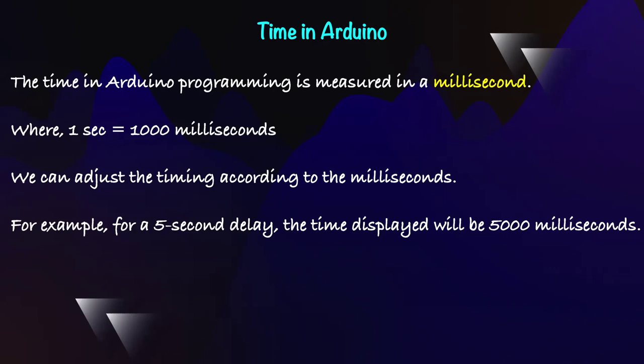Remember what pin 13 is, dear students? Digital pin 13, D13, where the inbuilt LED is. So you set pin mode 13, then it should be high and then low. It doesn't make sense because it would be on and off at the same time. So how will it make sense? If you include a delay in between.